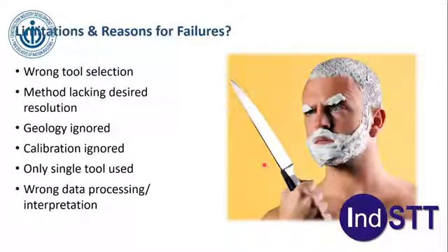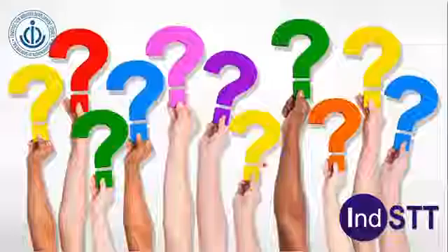Method lacking desired resolution. If your method is such that it cannot resolve a very small target at great depths, well, it won't work. Geology ignored. Calibration of the equipment ignored. Only a single tool used. I always recommend that for solving any problem you should use at least a combination of 2 tools, generally more, but that's the minimum. Or wrong data processing and interpretation. That completely depends on the experience of the professional who is doing the job.